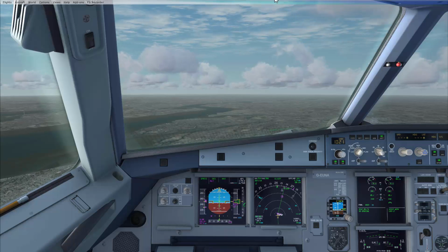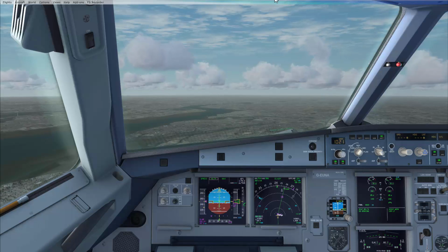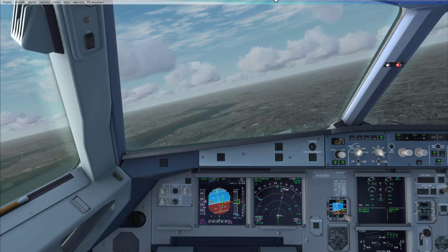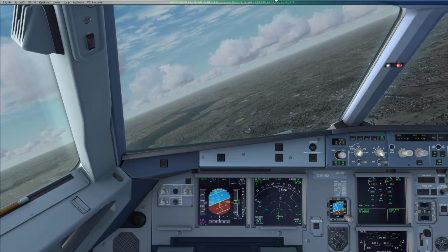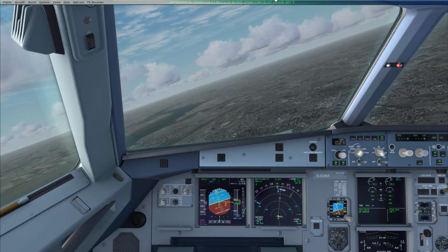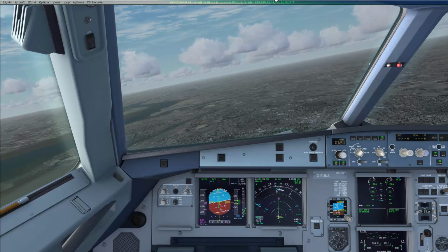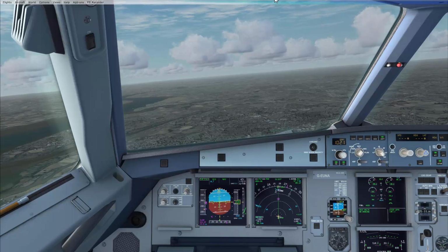Shortly, when the approach checklist starts, we'll go through that. When it's finished, I'll manually activate the approach phase on the captain's MCDU. In fact, we're approaching that phase now. I'll kick it off just a bit early, just to make sure that we stay ahead of the plane. I'll key 1. Approach checklist.